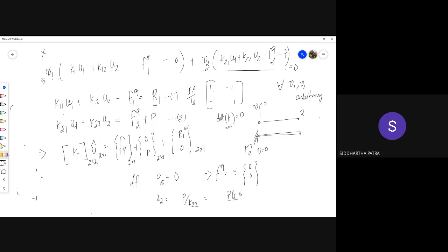In this case it would not be LE, it would be simply L, because LE equals L, because the element spans over the entire geometry. So U1 is fixed, then P divided by A is your stress, divided by E is your strain, multiplying the length. U2 is your total elongation.